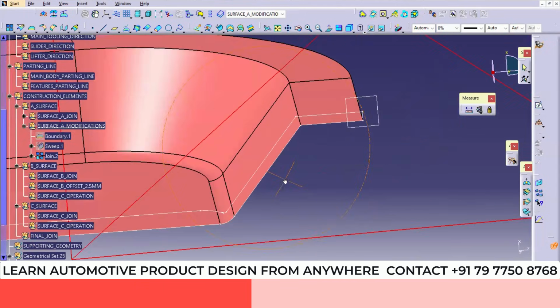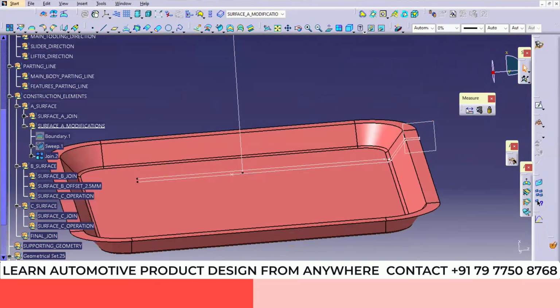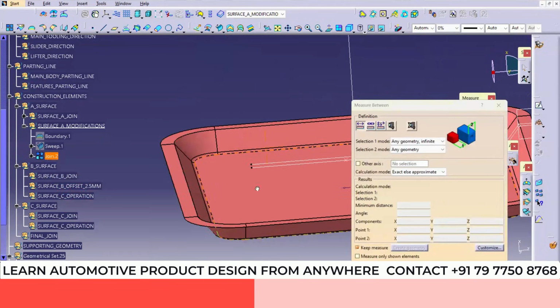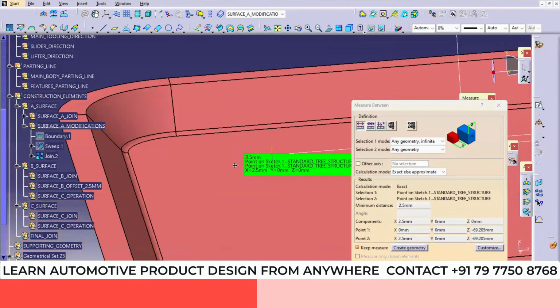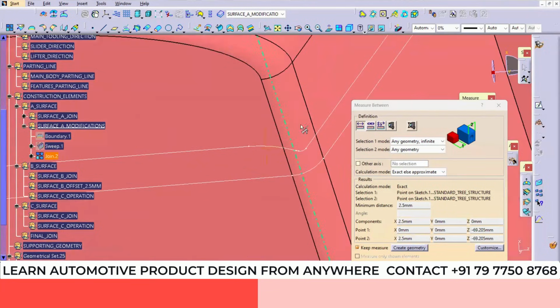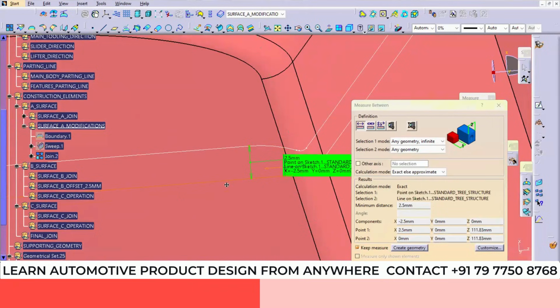Now next is class B generation. For class B generation, the offset value is required, right? So we'll check the offset value. You can always check with the point to point value, which gives the exact value, 2.5. Here there is no point to point, so you can check the line length. It is 2.5.